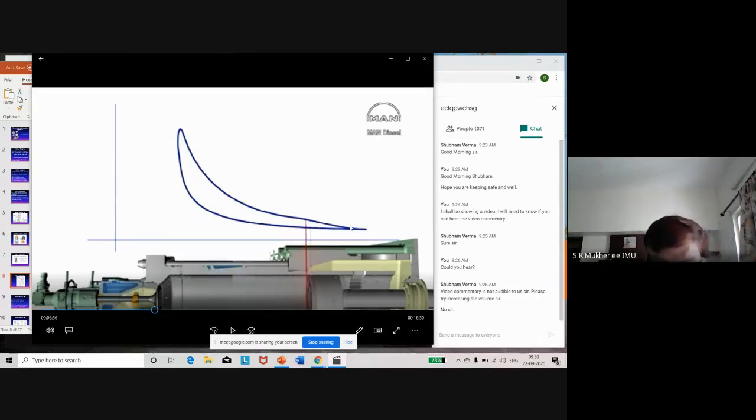In the process, when that mass of exhaust gas moves out, there's a region of depletion where it was. And that is the moment when the inlet port is opened and the atmospheric air will come in if it is normally aspirated. But most engines are supercharged, so the air will come in under a much higher pressure than atmospheric. So that air coming in will immediately start pushing out the remaining exhaust gases.